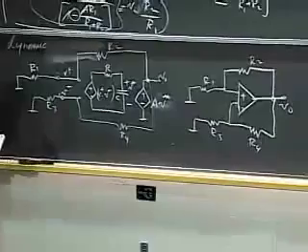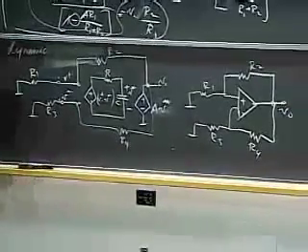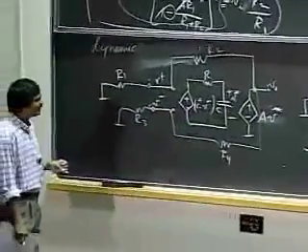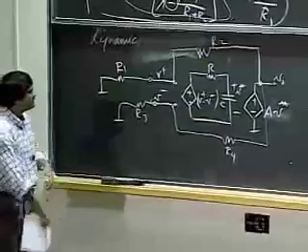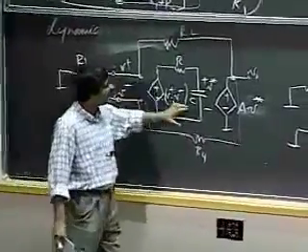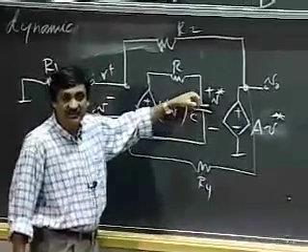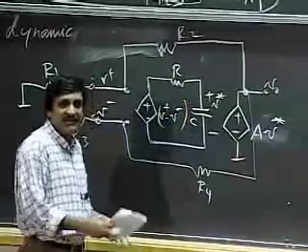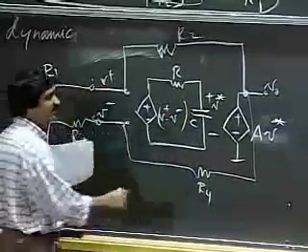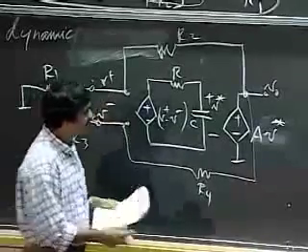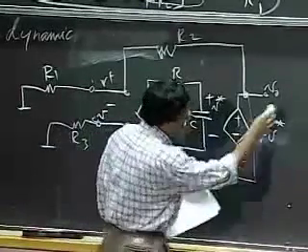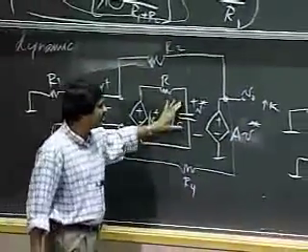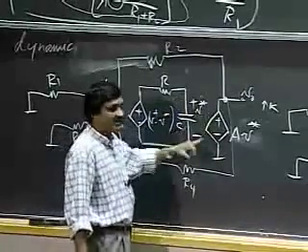So let's develop an equation of this circuit containing a capacitor using techniques that we already know. Just to give you some insight into what we're going to see, notice that if I make a small perturbation in the voltage across the capacitor, let's say by applying some initial condition onto the capacitor, then let's say the output changes to some value K. So the change on the capacitor must have been K divided by A.